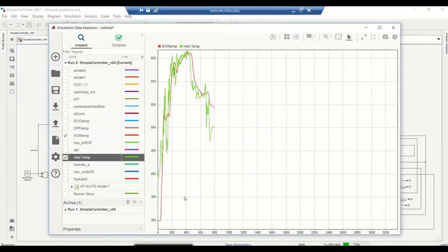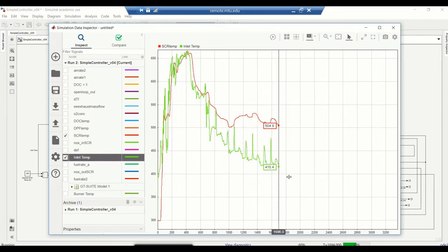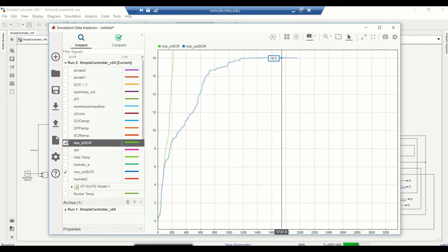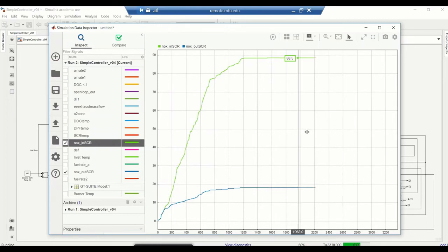Running this simulation, our primary goal is to increase SCR temperature to above 210 degrees Celsius to optimize NOx conversion without exceeding catalyst temperature limits or wasting fuel. The final PID tuning was done comparing overall NOx conversion efficiency and added fuel consumption of the burner.